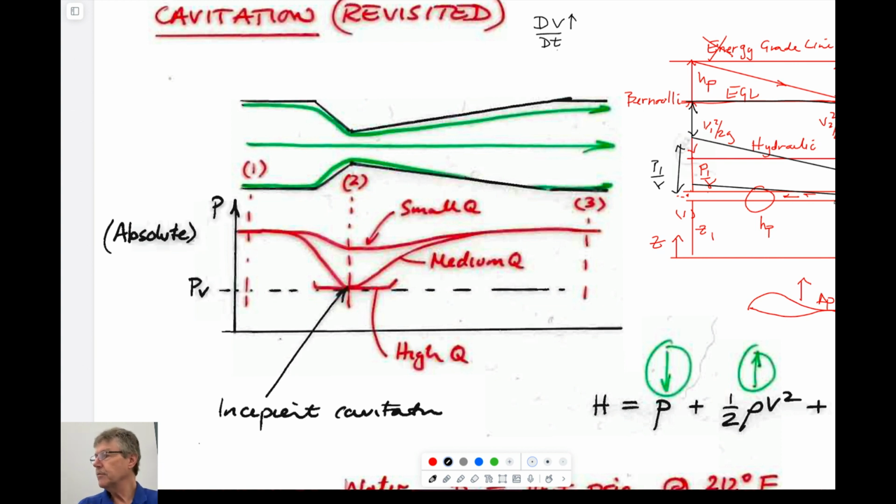So if you're in a capsule, a pig, as they call them, that's going down a pipeline, if you want to move fluids down pipelines, and they're different fluids, then you put the oil down, and then you put a pig, which is just a block, in the pipeline. You send that down with another fluid behind it. When it gets to its destination, you pull the pig out, and then you just route the flows into different locations. So if you're going down in a capsule, then I've lost my train of thought why I was saying this, then you would experience different pressures as you go down here. And because the velocities are different as you go down here, the velocity of that pig experiences a change in velocity with time as you go downstream. So that's an acceleration for you as you're in that pig.